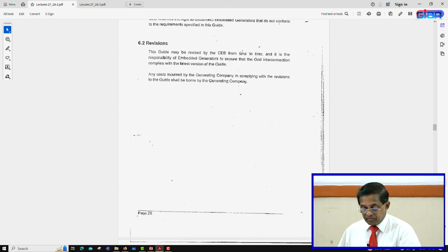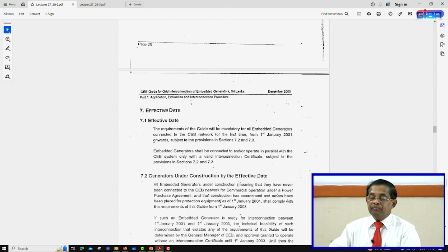There are also accuracy classes, because in a household meter, normally it is about a class 2 meter, that is, there could be about 2% error. But for bulk power selling like this, you must go for at least class 0.5, though those meters are a bit expensive, and the CTs and PTs should also have similar accuracy. Otherwise, your metering will be erroneous, meaning you will have a big loss on your part, or on the other side the utility will lose. Therefore, for big energy sales you should go for higher accuracy energy meters like class 0.5.